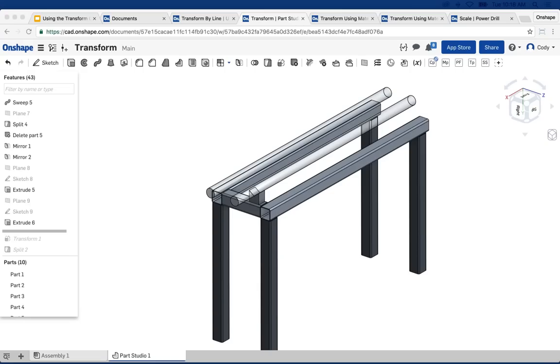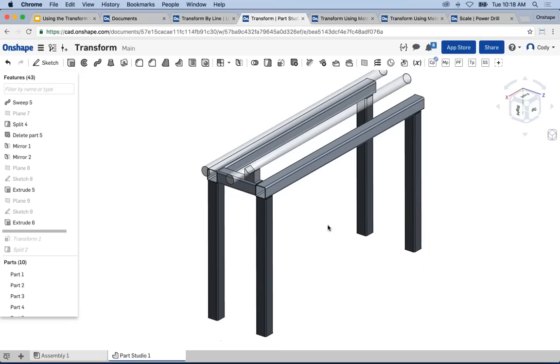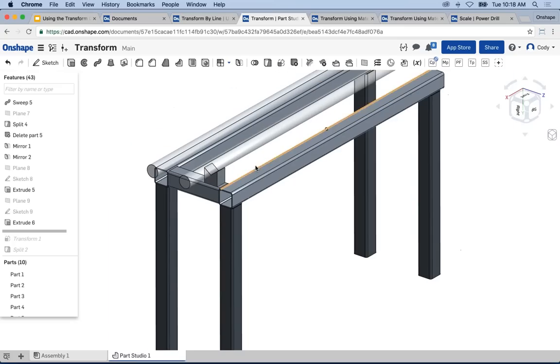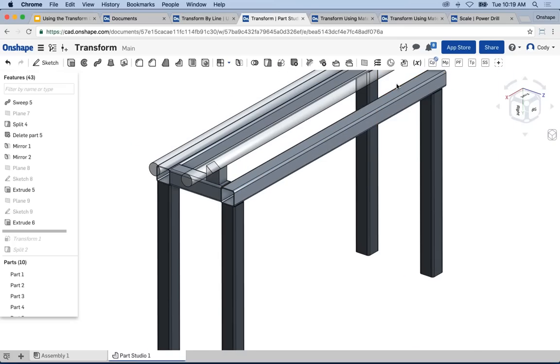The other thing to consider is in the Part Studios, it's really only important to model a single instance once. So if I were modeling this Part Studio, for example, really I have this V block and this frame piece. I have them patterned several times, but it's really quantity 5, instance 1, right?